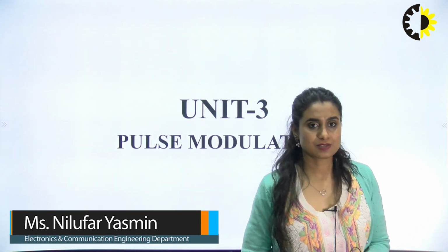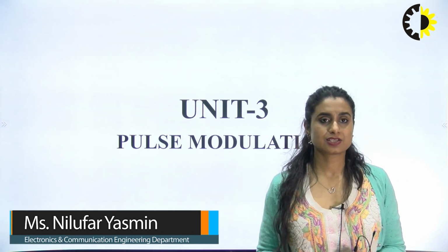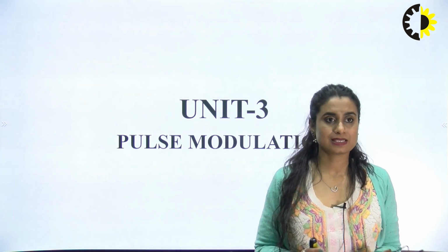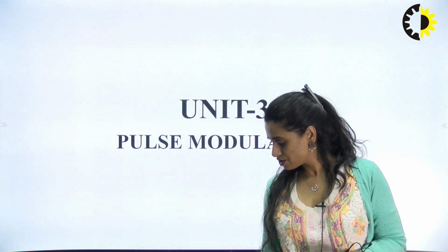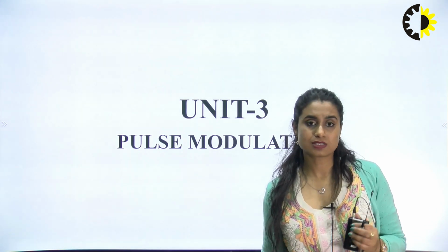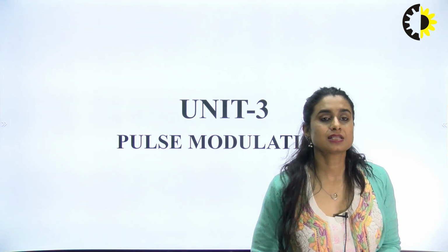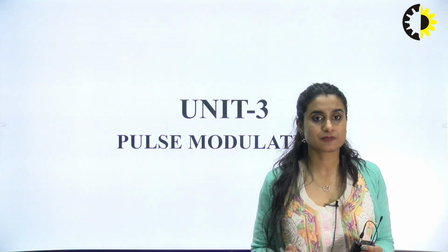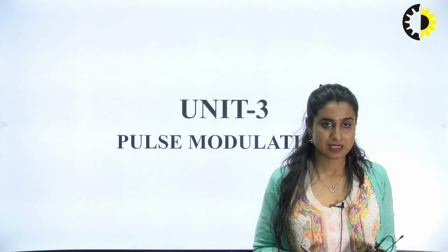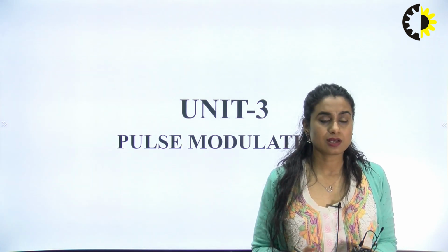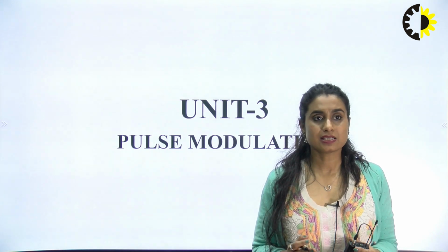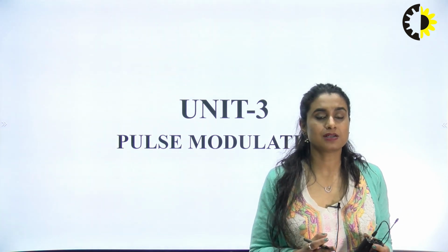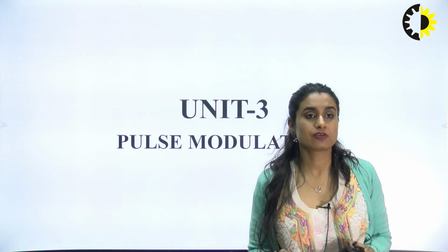We're going to talk about pulse modulation. This lecture is in continuation with the previous lecture, where we have already discussed the basics of pulse modulation. To give you a brief overview, modulation is the process of altering the characteristics of a high frequency carrier wave with respect to the instantaneous value of the message signal. In pulse modulation, the high frequency carrier that we consider is not a sinusoid, it is pulse in nature.